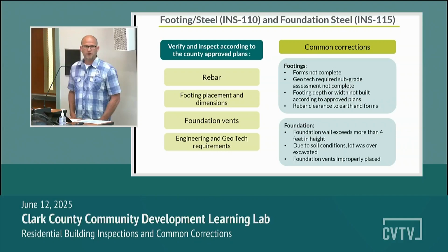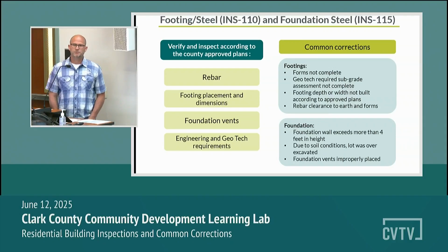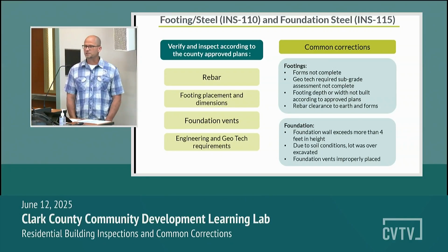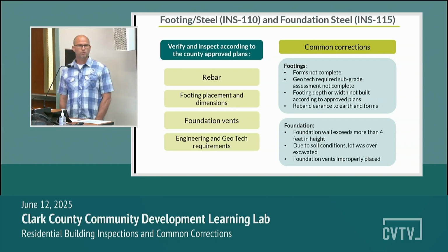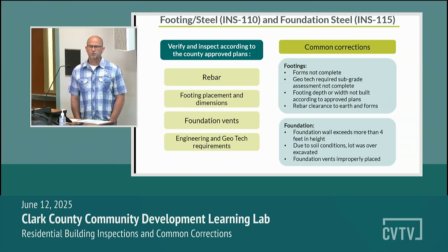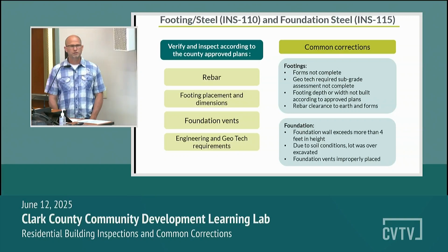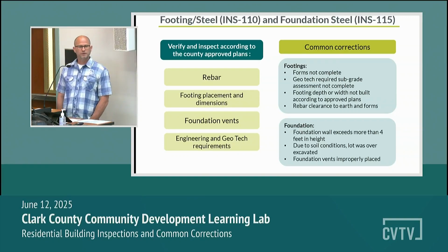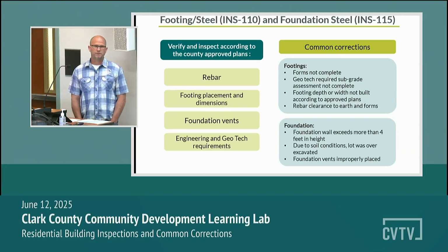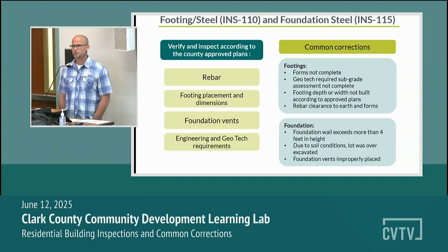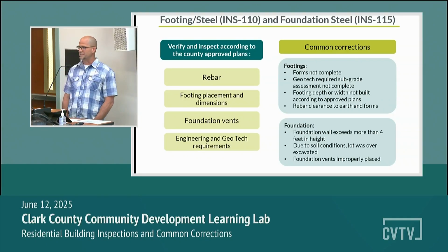Now, once we finish with the foundation or the zoning inspection, we're going to do the footing/foundation inspection. Because at this point, we can't do the zoning inspection until we actually know where the building is being placed. So now that the building footings and foundation are in place, we will go off of the foundation page on the structural documents and we'll check the rebar. We'll check the footing dimensions and sizes.